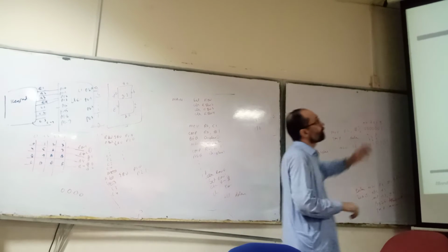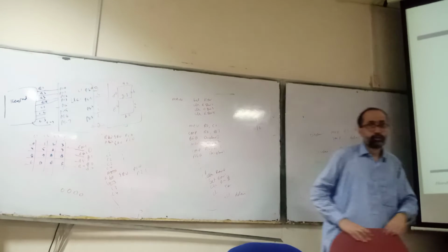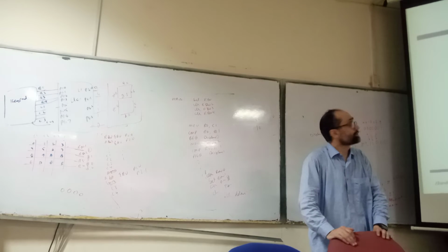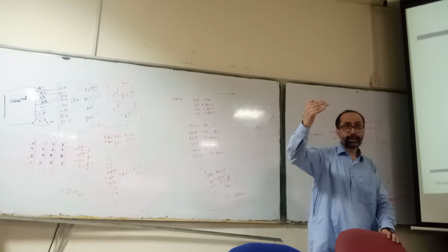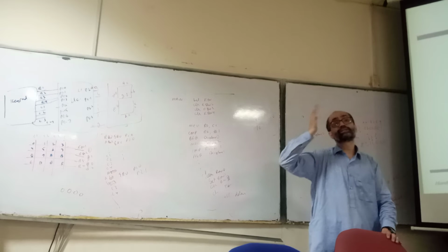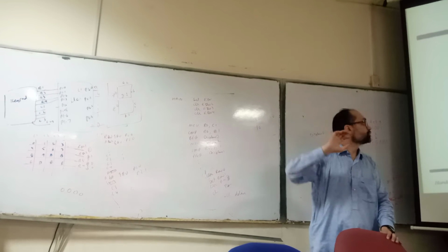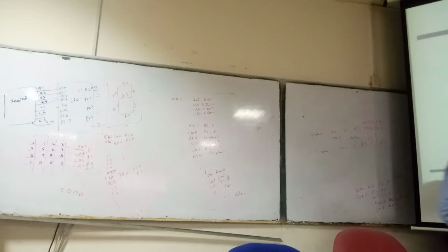So if you want to have a keypad controller and we want to control this keypad with a simple microcontroller, there are two mechanisms. First we drive the rows and scan the columns, or we drive the columns and scan the rows. And actually this is the key code.